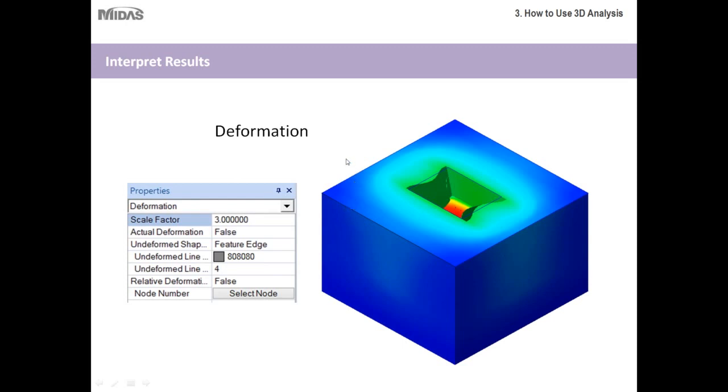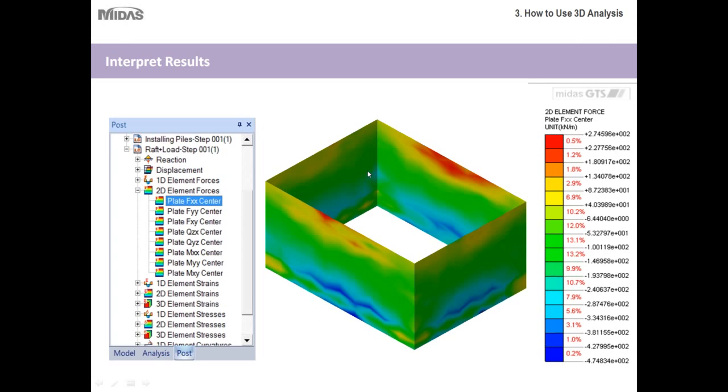Okay, and then here are the results for my retaining wall. As you can see, what you can do with your model is isolate certain parts. So later on, if you just want to see your retaining wall, you can turn those elements on and focus purely on the results of your retaining wall. Reading the results is a similar process. The maximum results are typically in red, and you'd use your legend to reference what those results are.